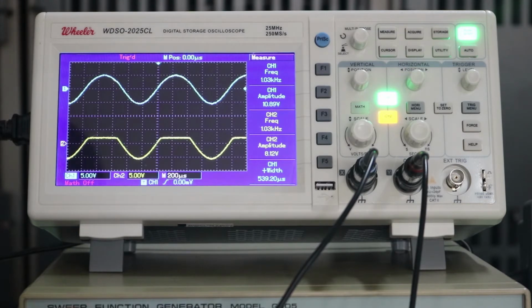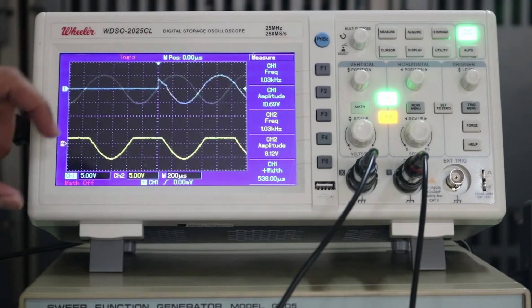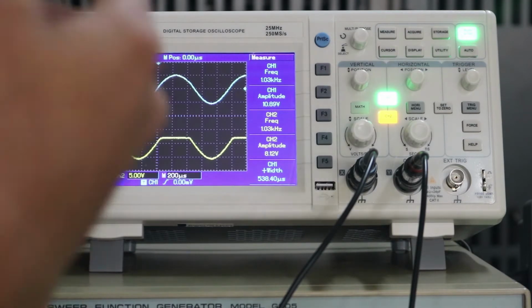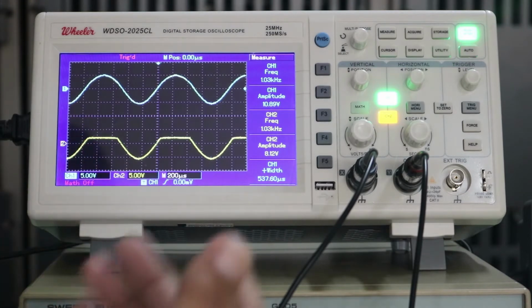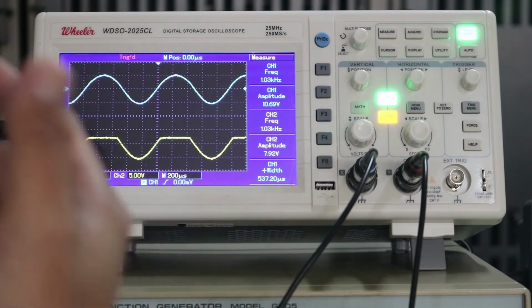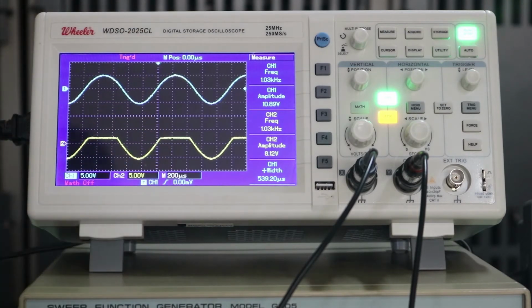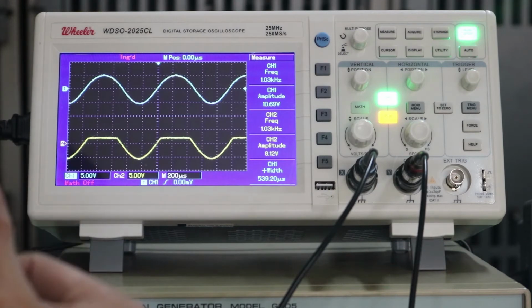As you can see, part of our waveform is clipped or removed. So this clipper circuit is a positive clipper, which means the part of the positive cycle has been clipped. Contrary to the positive half-wave rectifier, where all of the positive cycle has been removed, in the clipper circuit, only a portion of the positive cycle of the signal will be clipped or removed.